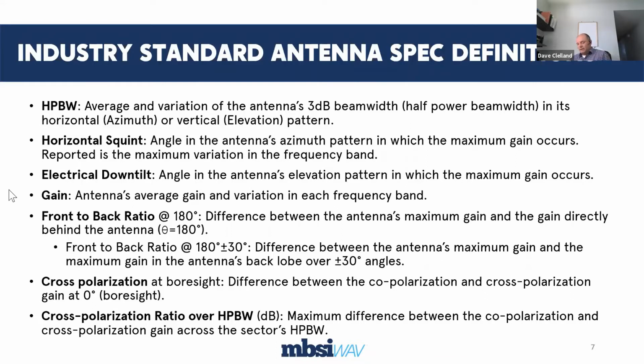Now, there are a couple of manufacturers like Mars and a few others that make a variable down tilt antenna. It can be a mechanical down tilt, where a screw adjustment on the bottom of the antenna, either with a screwdriver or with an Allen key, will change the relationship of the elements inside the antenna, and you can adjust the down tilt.